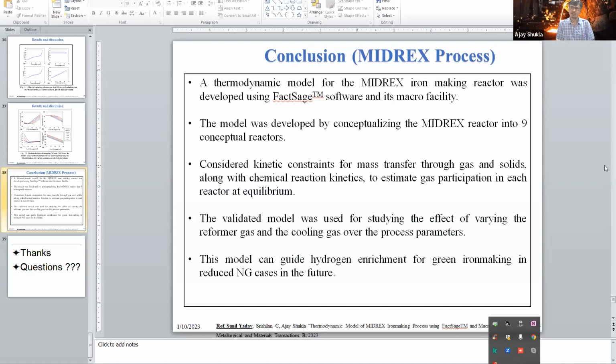Okay, so thank you, sir, for this question. It's a very good question. In fact, you know that the gangue mineral inside the iron ore is the main reason for this slag generation. For example, we know that in the case of blast furnace, we have a limit on the gangue material, so that is why it cannot take iron ore beyond a certain Fe level. But in the case of the Corex process, we already have a lot of slag volume which is coming from the ash content of the coal. And depending upon that, we need to charge more and more limestone, so it is going to have another cyclic effect.